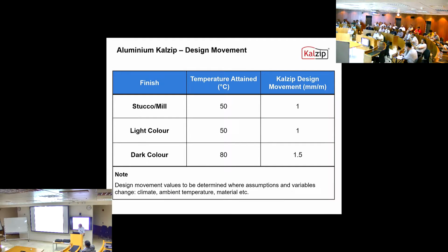So we simplified that analysis to look at design movement by length, not by degree, or by 10 degrees, or 20 degrees. It's just by length, so it doesn't matter the temperature. The first factor is length, millimetre per metre. Which temperature difference? It just doesn't make any difference.